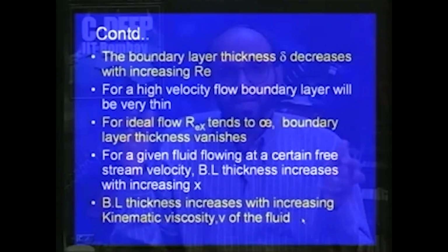From this we can finally summarize that, as far as boundary layer formation is concerned, the boundary layer thickness, or how much of the boundary layer effects are to be considered, depends upon the kinematic viscosity, upon the shape of the body over which the flow is taking place, and upon the Reynolds number or the fluid flow velocity. Depending upon all these parameters, the nature of the boundary layer changes, and we have to consider the boundary layer accordingly for various solutions.